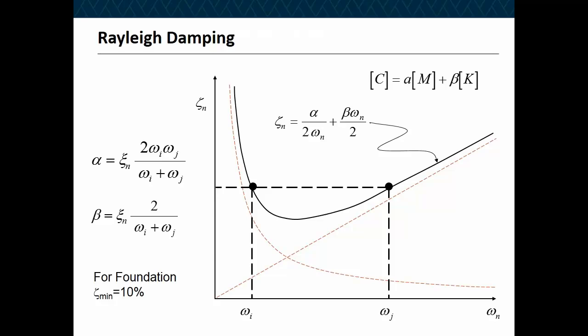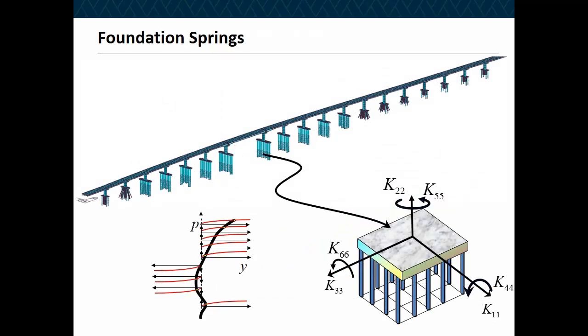And it's an iterative process because the stiffnesses are developed for a given displacement. We don't know what kind of displacement we're talking about. That is the drawback in the substructure model, that you have to guesstimate a stiffness based on a given displacement and go back and forth until you converge to a stiffness that you like when you look at the global model.